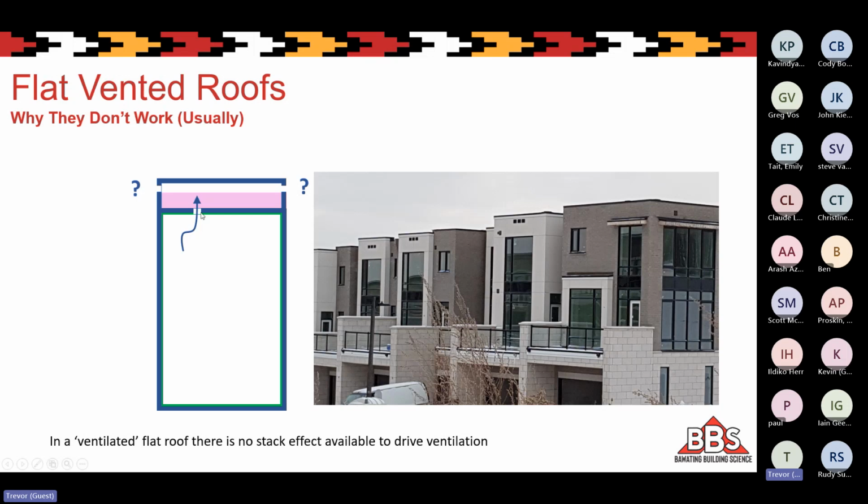The problem with that is we don't have very much at all, or maybe I really don't have any stack effect in the attic to help us ventilate. We have stack effect in the building that's still putting that warm, moist air into this space, but we don't have the benefit of stack effect in the attic to drive that warm, moist air out. And we start to see accumulation because we don't have a height difference between the ventilation intake and the ventilation exhaust.